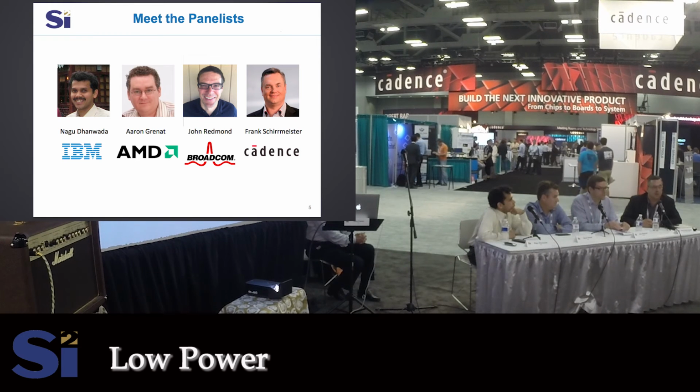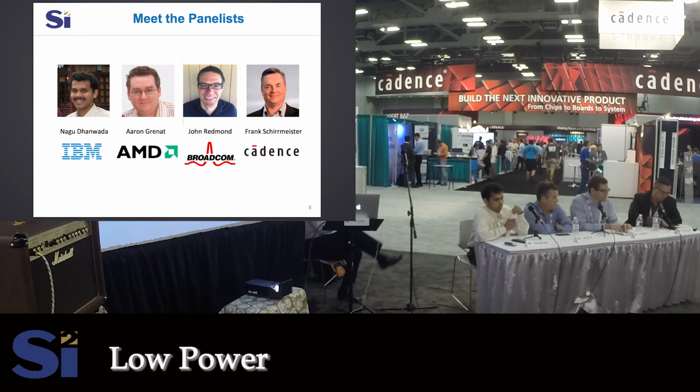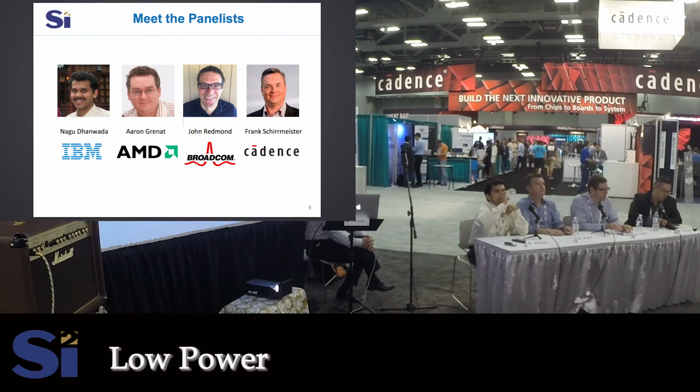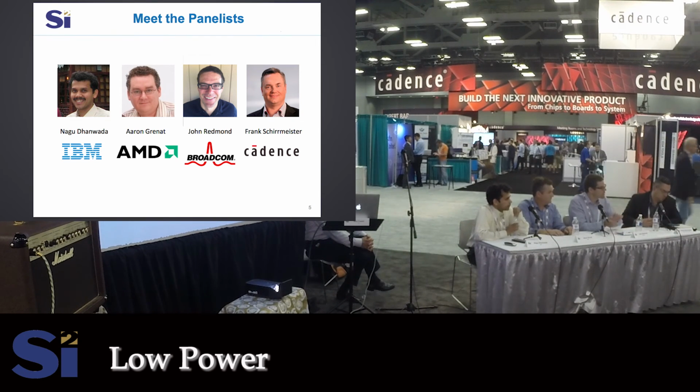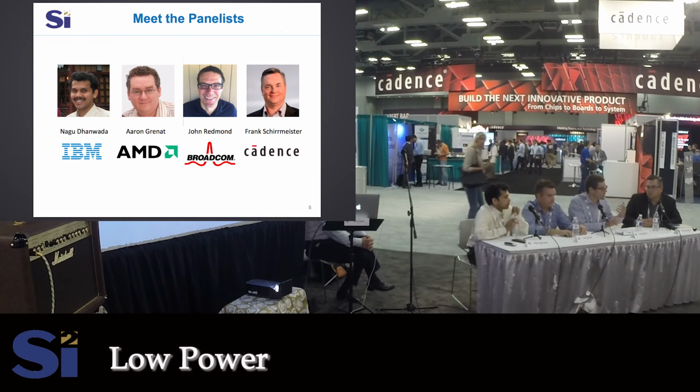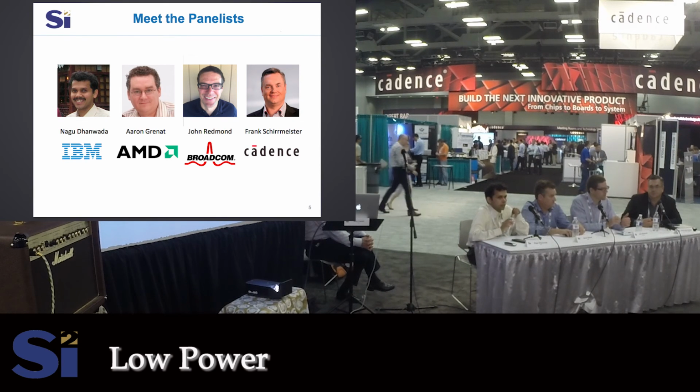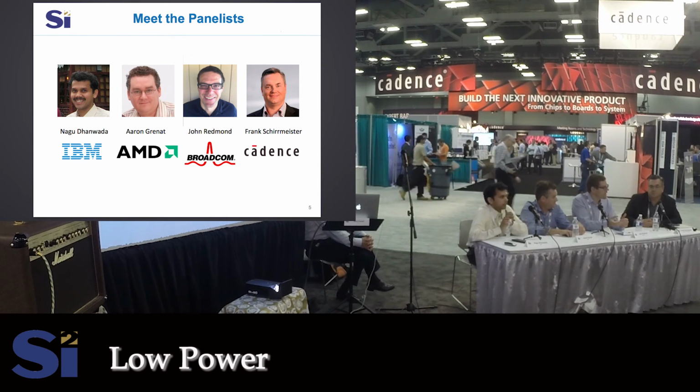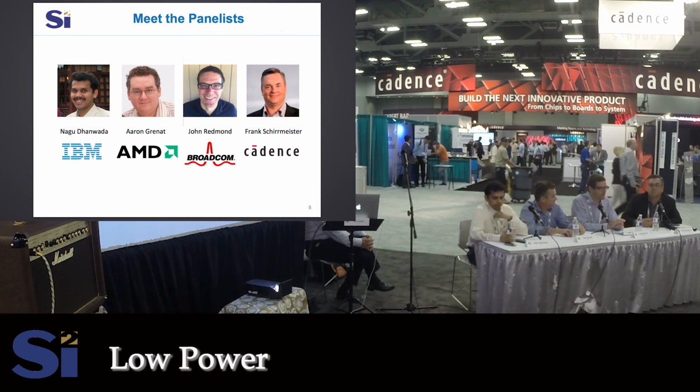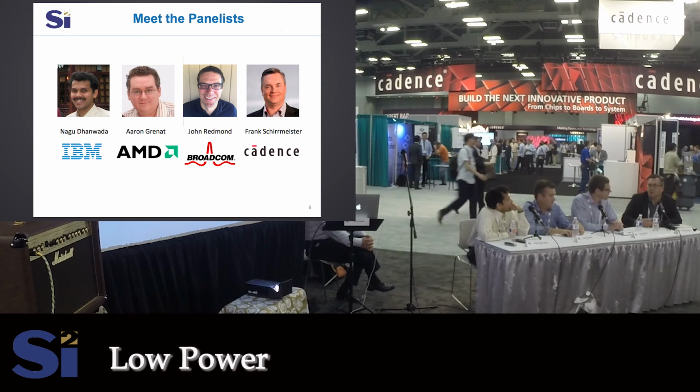And the accuracy at the RTL level is also bigger. And we do get a lot of value out of emulation, and we've caught a lot of power bugs with emulation. But the problem that I'm trying to address is that emulation comes too late in the design flow. We want to do something early on in the design flow to do exploration. Right. So oftentimes with emulation, when it's actually running mission mode software, all the architectural decisions have been made. You can't make any changes anymore at that level.